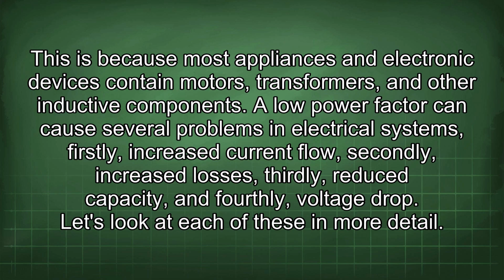A low power factor can cause several problems in electrical systems. Firstly, increased current flow. Secondly, increased losses. Thirdly, reduced capacity. And fourthly, voltage drop. Let's look at each of these in more detail.